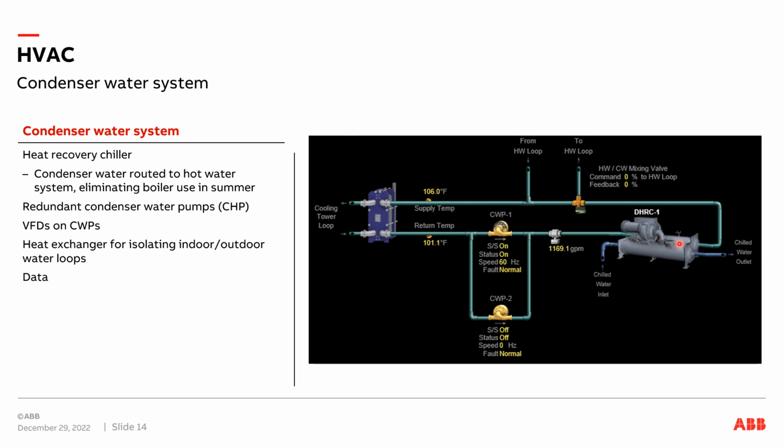My chiller is inside my building, and I don't want it to be 130 degrees in that room. So what we have is a water-cooled chiller. Some people would put these outside and it would be an air-cooled chiller, but we have ours inside, so it's water-cooled. I use water to get rid of that heat. This water comes through the chiller and picks up heat from the refrigeration cycle. So you'll typically see one of two things.